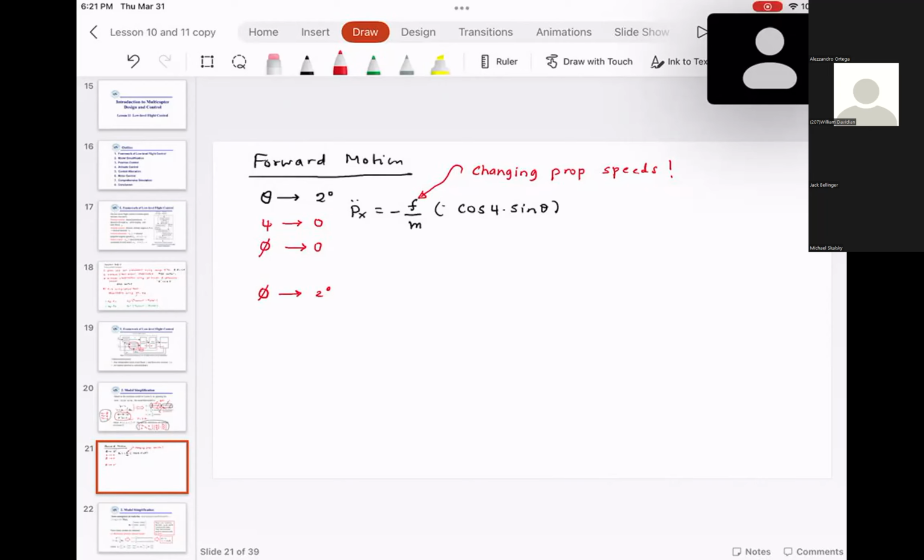If you want the system to be stabilized at high angles, then you will have to use maybe model predictive control, or some type of advanced control algorithm, or maybe a gain scheduling algorithm, some type of control algorithm that is better than a simple PID.